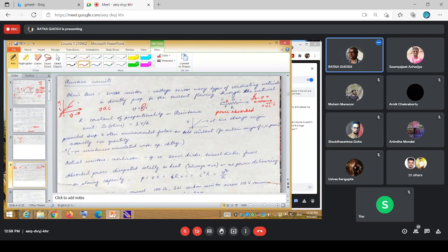Current is the dependent variable depending upon the voltage. Yes, usually you have voltage sources. Since we are talking about voltage sources, voltage is the independent variable with respect to which current is generated. So as a result, this would be the typical IV characteristics that you will see in several of the curves. However, this one was voltage to current. So naturally, the slope in this one would be nothing but 1 by R. It's a linear curve, so 1 by R.